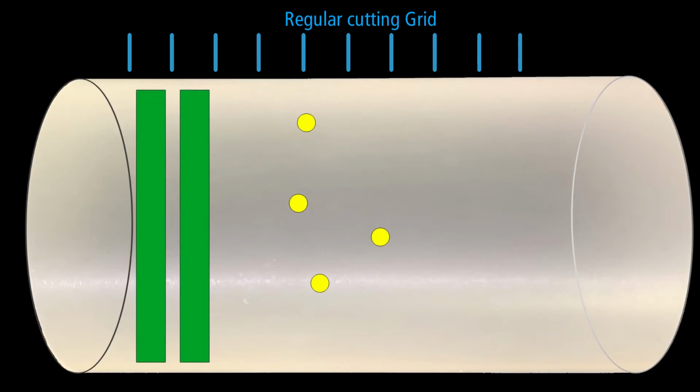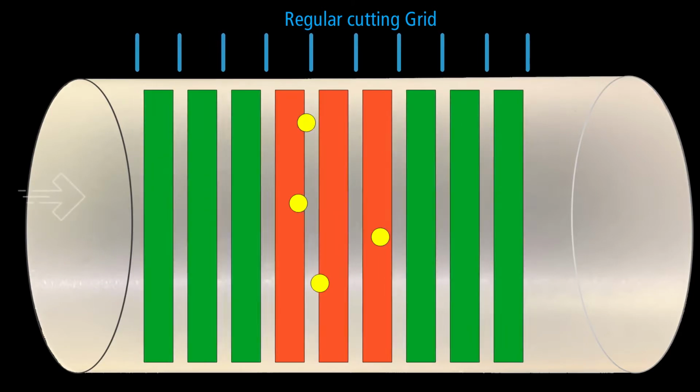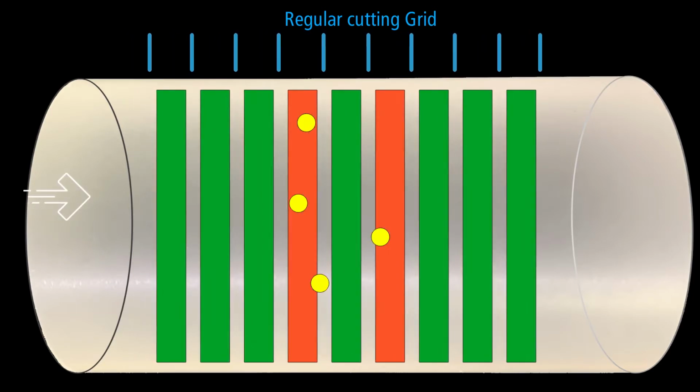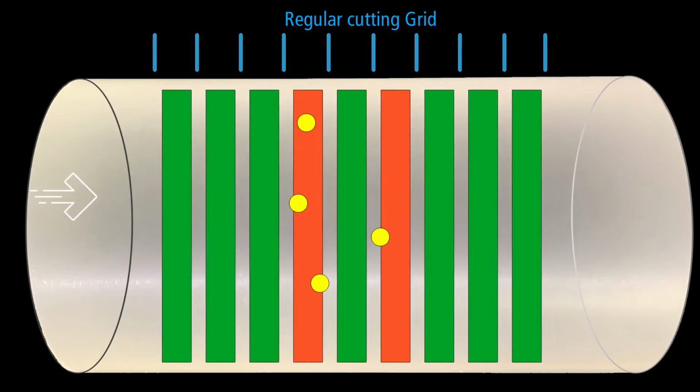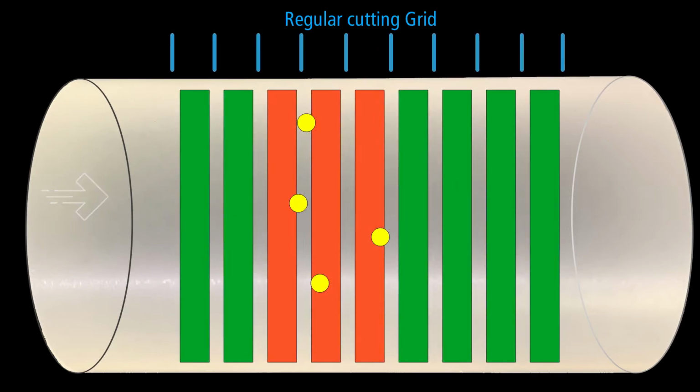Assume our core has a few volume defects, for example, a bubble or a microcrack, which makes the corresponding wafer defective. It would be useful to put as many defects in the gap as possible so they get removed, right? So, we could slightly shift the core along the grid and see that when some defects end in the gap, we get an extra defect-free wafer.